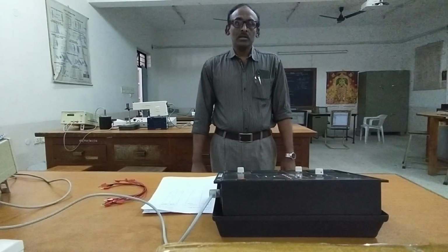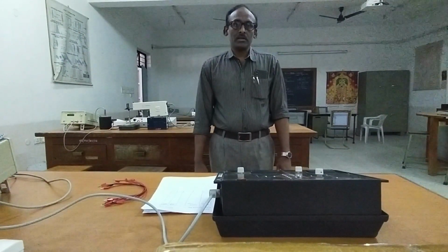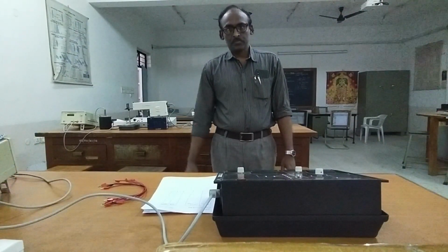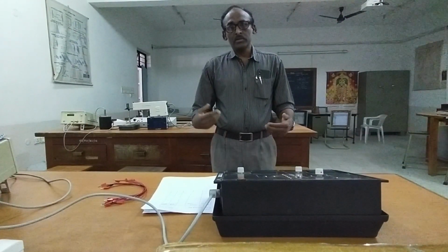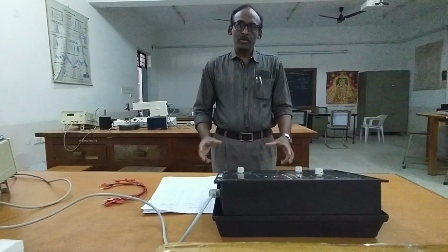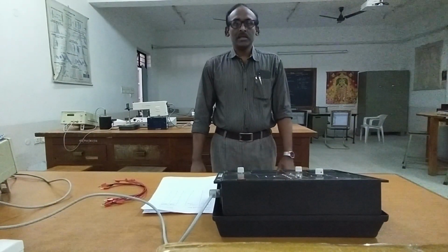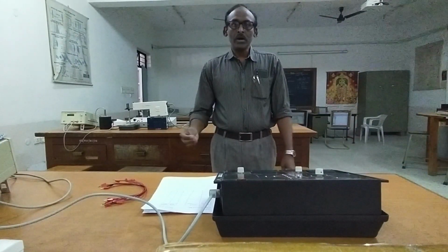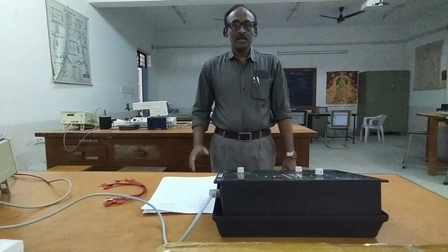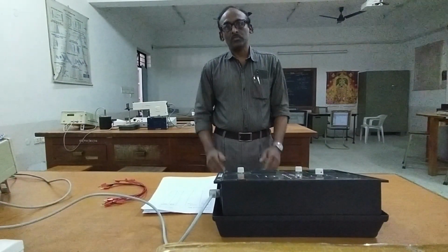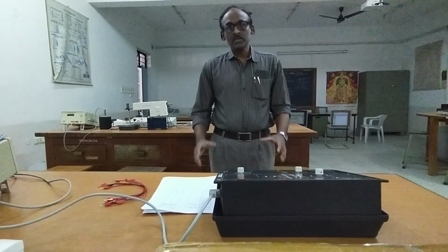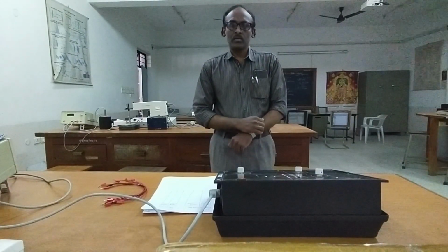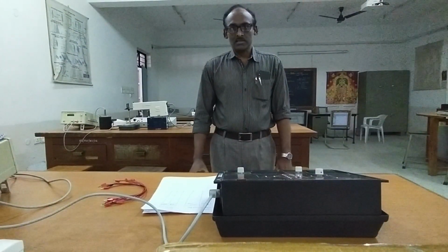But when an electron in the solid falls into a hole, then a covalent bond is regained. Thereby, the amount of energy supplied to break a covalent bond is the same as the energy required to form a covalent bond. Therefore, when an electron recombines with a hole, it loses energy and gives that energy in the form of heat or in the form of optical energy. If that is given in the form of optical energy, you can use that material to make an optoelectronic device such as an LED or laser.